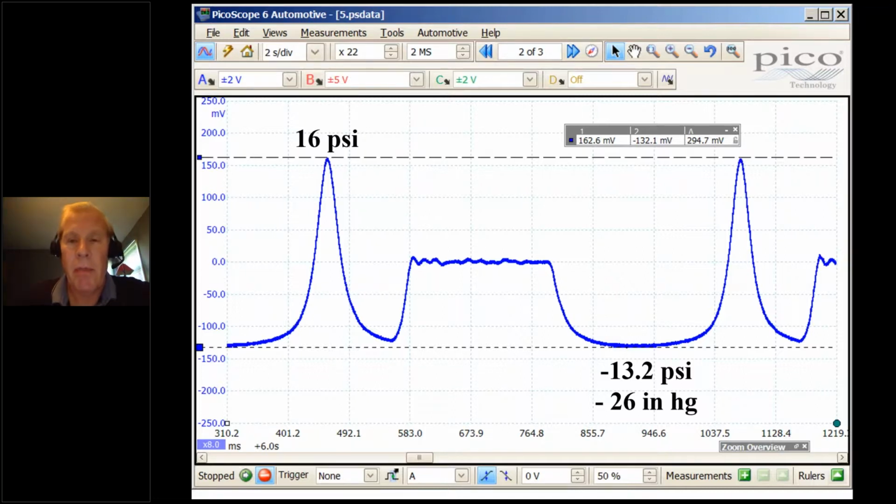So the question becomes, and I expect you to answer this before I get there, do I have a big hole in the cylinder? Is there a chunk of that exhaust valve that's fallen off? Is there a hole in the piston? Did the nitrous burn a hole? Did they break some rings or damage the wall? I mean, what did they do here to make this compression so horrible? Let's see if we can get a handle on it.